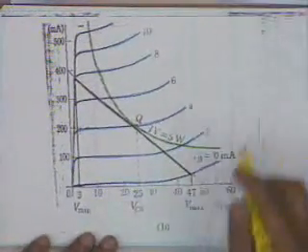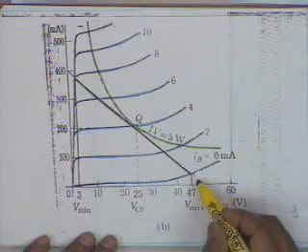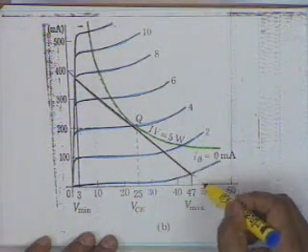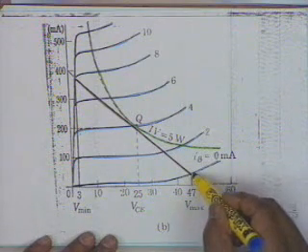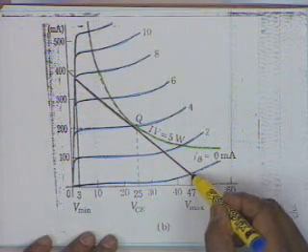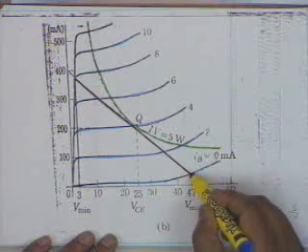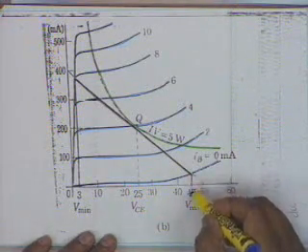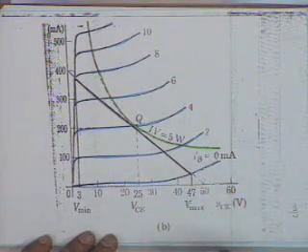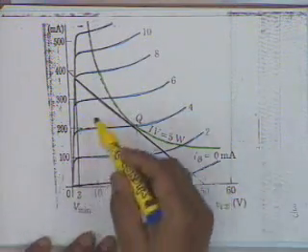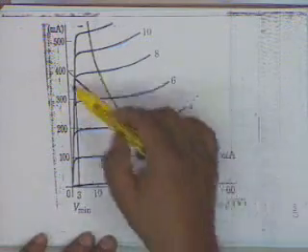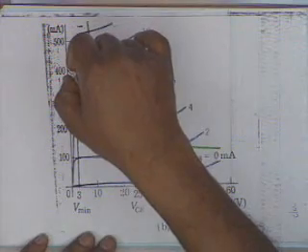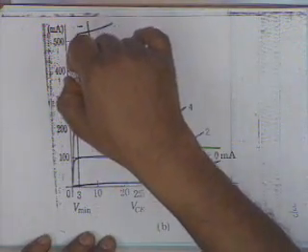All right. Now, if you look at the actual characteristics, you notice that the AC load line, the red line, cannot quite go to 50 because it crosses the IB equal to 0 milliampere line, and therefore this must be your maximum VCE. You cannot go to 50, you can go only up to about 47. In a similar manner, you notice that the curve cannot go right up to this point, because the saturation part of the characteristic is to be exceeded.